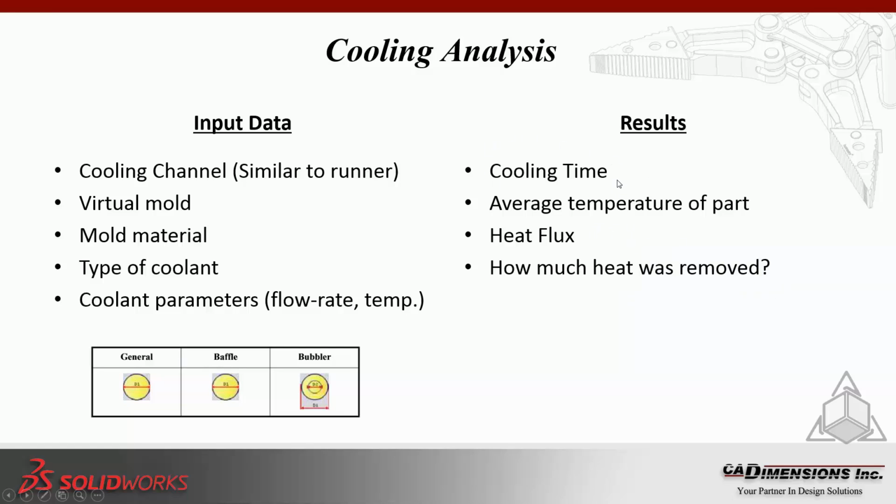In terms of cooling time, one thing that you can do is proceed with cooling analysis: run the cooling analysis first, get the cooling time, and then put that cooling time into your warp analysis and see what type of warpage you're getting based on that cooling time.